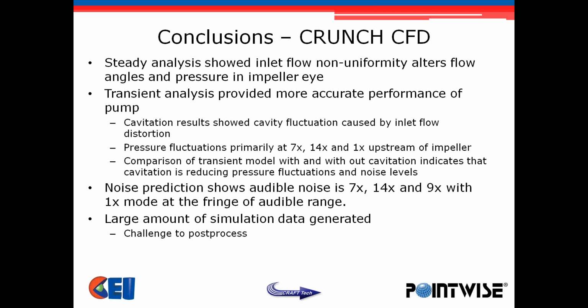And what we were able to determine is that the cavitation was not a primary source of the noise. However, it did introduce some compliance into the system that actually affected the amplitude of the fluctuations and reduced the noise level some. We did an acoustic analysis to predict what the noise was from an upstream observer, and we were able to pull out the source of the noise with respect to the unsteady fluctuations in the pump system.